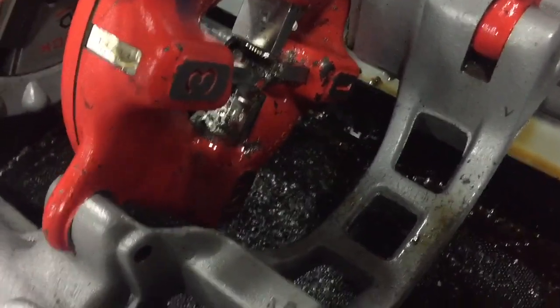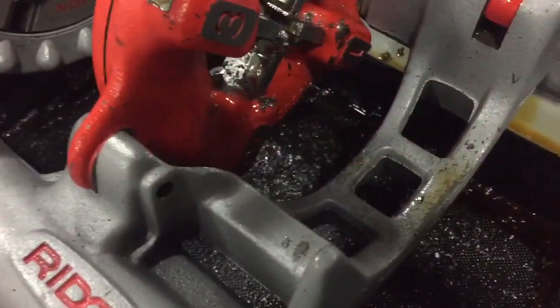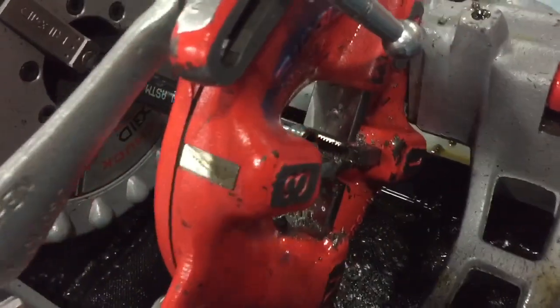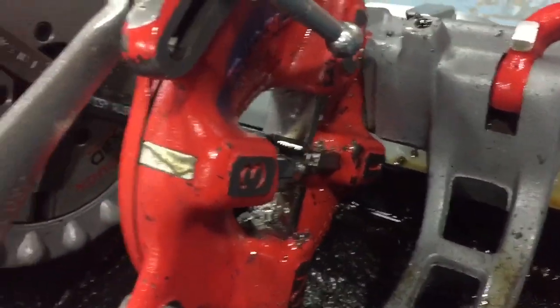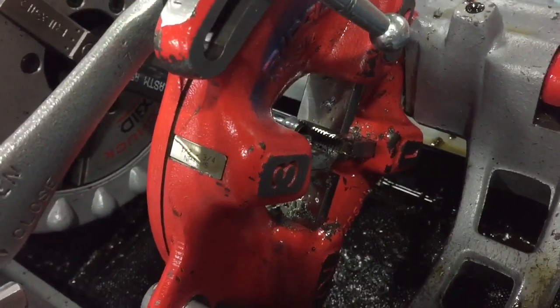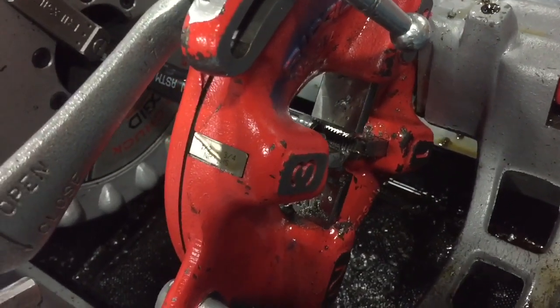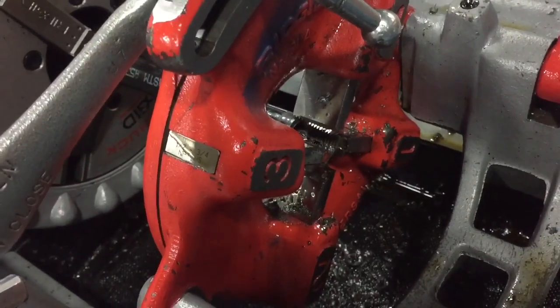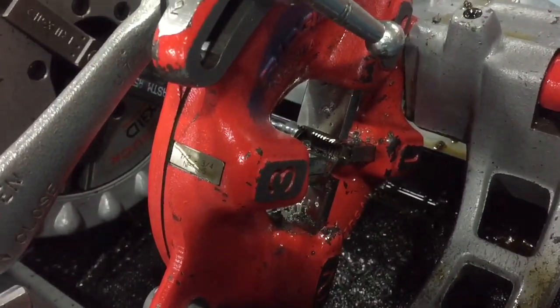I'll just move it in here with the wheel over here, close, and we want to be applying some pressure. I'll be continuously applying pressure, and once it starts grabbing and makes about 2 or 3 threads, we can stop applying pressure, and then the machine will just take over, and it'll just keep threading the pipe.